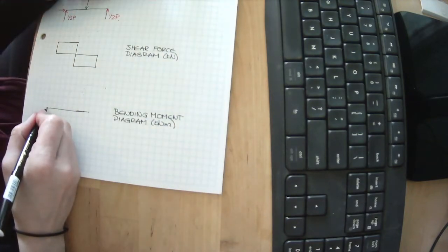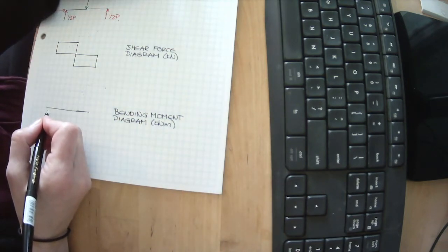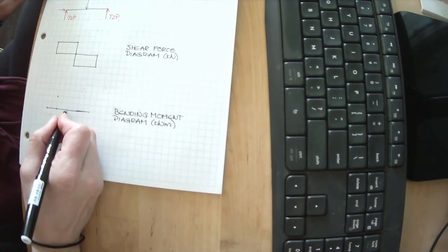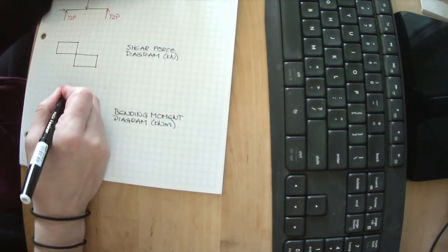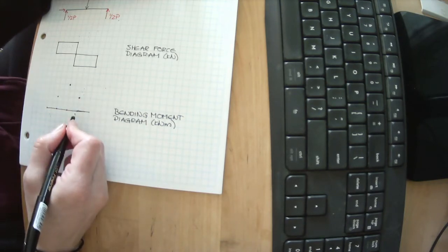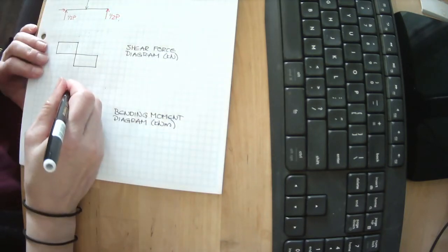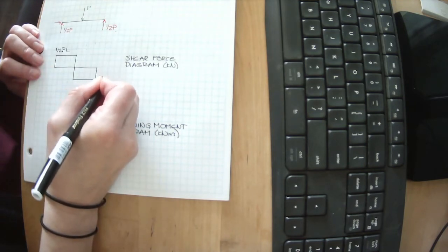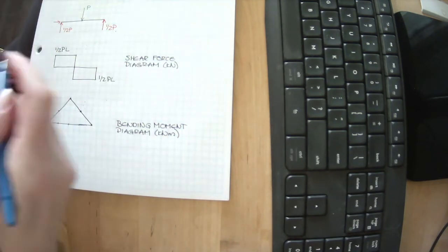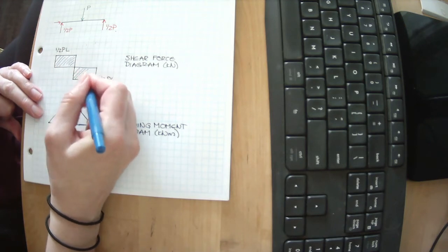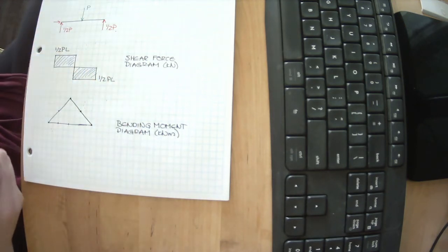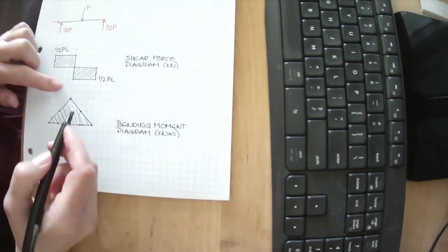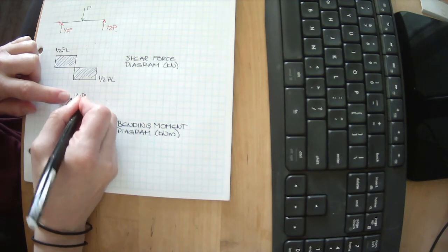All right. At x equals 0, the moment is 0. At x equals 1/4 L, right here, we had 1/8 PL. At half of L, it didn't matter what side of the point load, we had 1/4 PL. At 3/4 L, it was 1/8 PL. And at the full length, the moment was 0. This is 1/2 P, and this is 1/2 P. Remember, once we're drawing it on the shear force diagram, we don't care so much about whether the value is positive or negative. We like seeing where it crosses over into positive and negative. And then our bending moment diagram, right up here, our highest value was 1/4 PL.